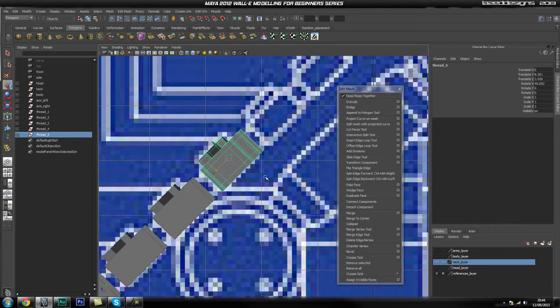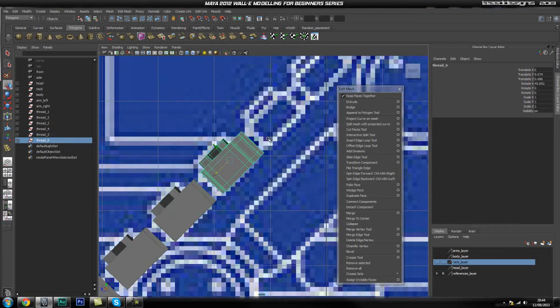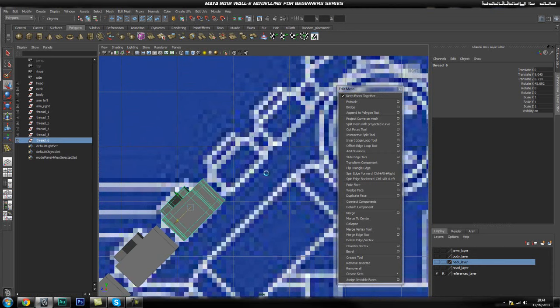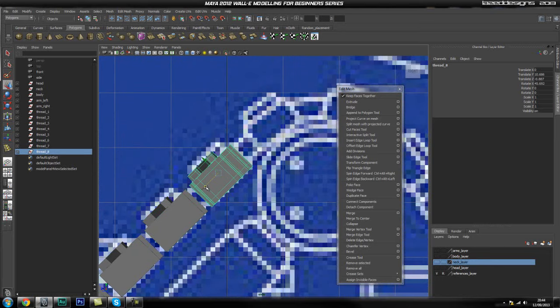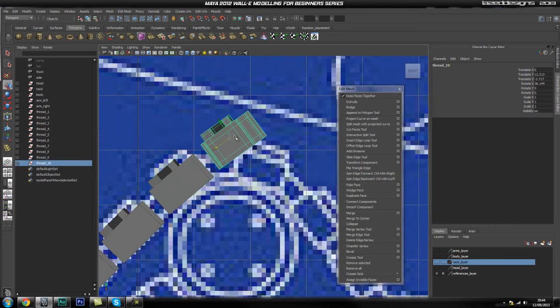And I can also press Shift D and it will duplicate and move it the same amount that I did last time, and now I only have to do little adjustments, okay, like so. And obviously in a minute I'm going to have to start rotating them a little bit. So now for this piece, it's going to rotate quite a bit downwards.